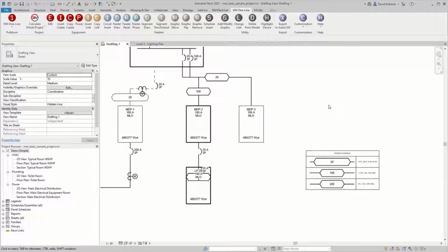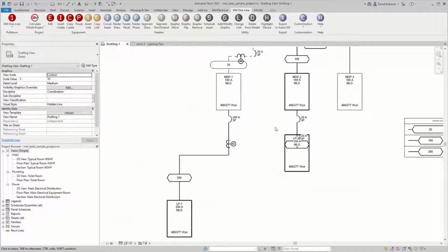First, if you please update one of these panel circuit breaker or overcurrent protection device in the DEV, and then run calculate the whole project, see if it's updating, and same thing for the feeder tag. If we update it from edit, like change it to a different wire size, and by the time we run DEV, let's see if it's updating, like getting the new tags.